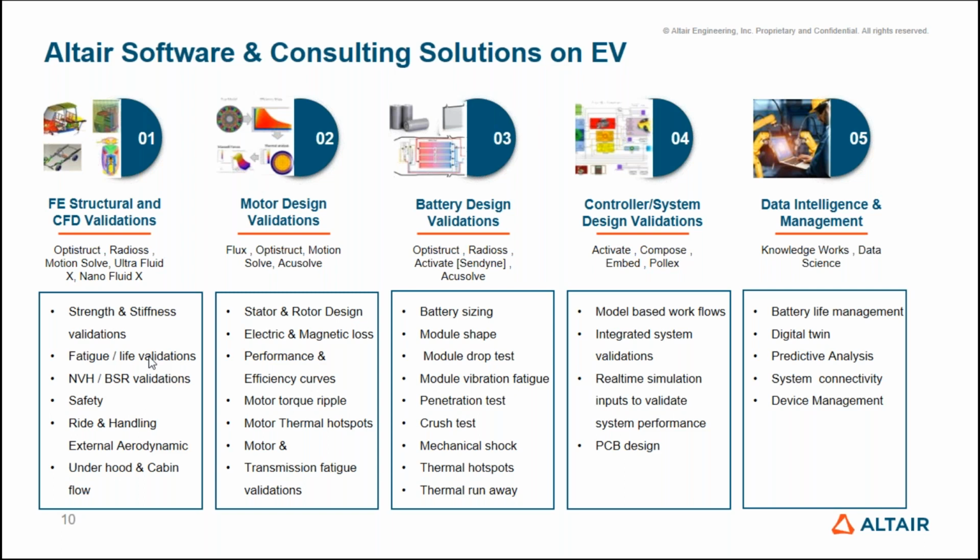You can calculate the torque ripple and minimize it, and find out the motor thermal hotspots, where you want to see what temperature comes out of the motor while it is running. Then you can also consider these electromagnetic losses to check the vibration generated by the motor. All of this you can do with the help of these solvers: Flux, OptiStruct, MotionSolve, and AcuSolve.